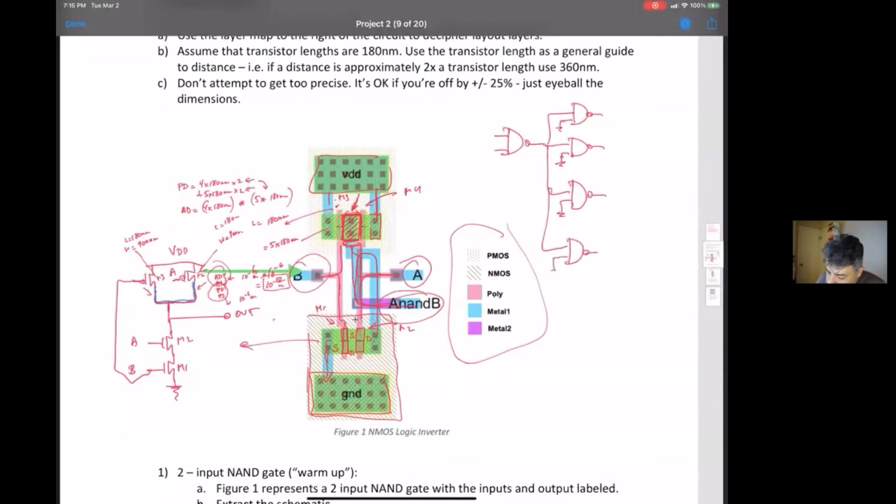And you want to basically, by having 2 pulse trains, one twice the speed of the other, so this is A, this is B. It doesn't matter which is which. Then you get all the combinations: 1, 1; 1, 0; 0, 1; and 0, 0. For each one of these, you can see what the output is and prove that it's a NAND gate from input to output.